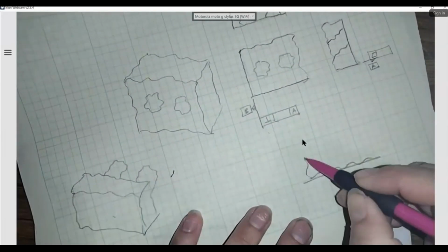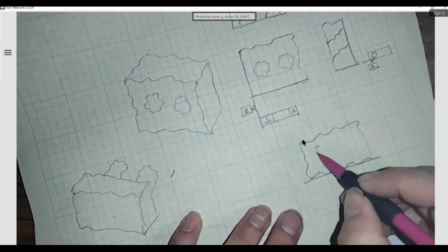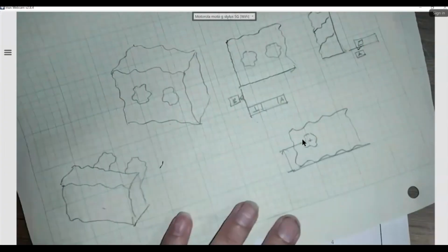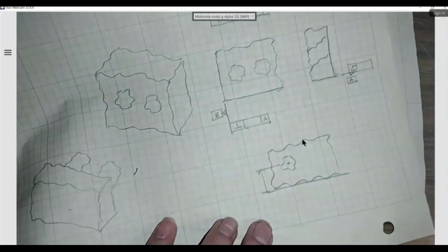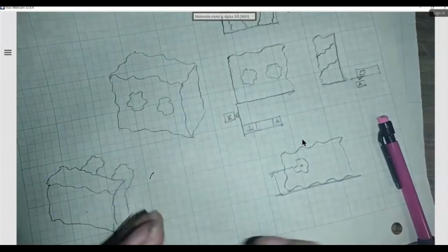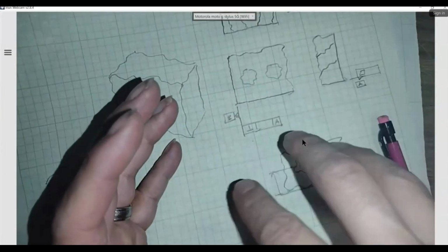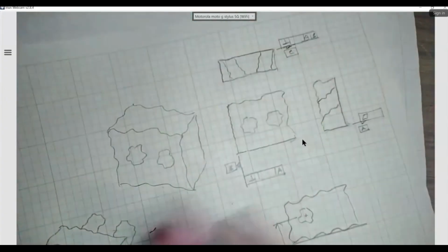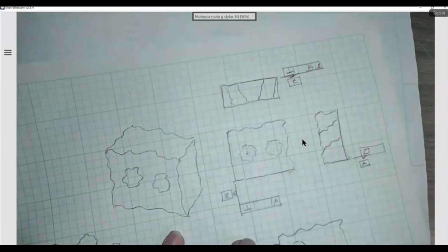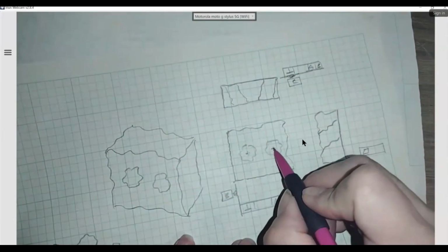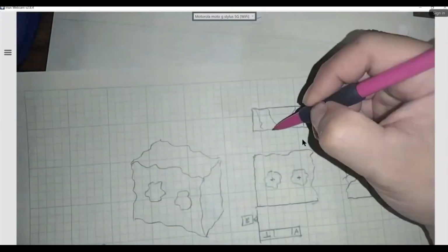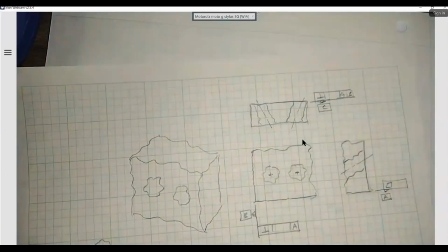And all my dimensions will originate from the datum to where the axis is going to be, right? And in order for me to define the axis, I need to go inside of the hole and expand. The same way that I told you for the pin, it's just like a drill, right? You gotta expand and define the axis. Okay, how do I control the hole? Well, I am going to expand and define the location of that one. And that means it will define an axis that looks something like this. And it will also define an axis that is actually crooked a little bit.